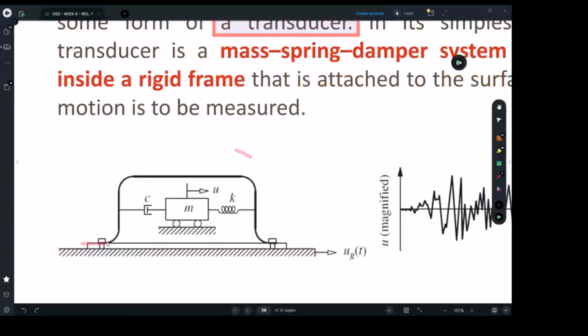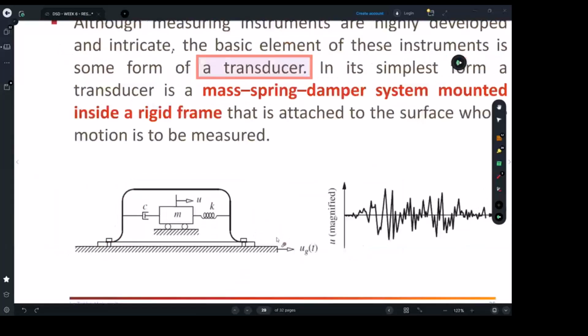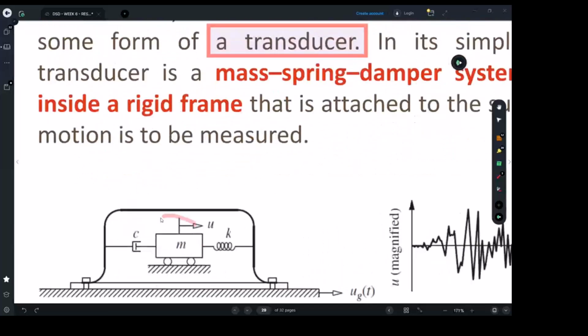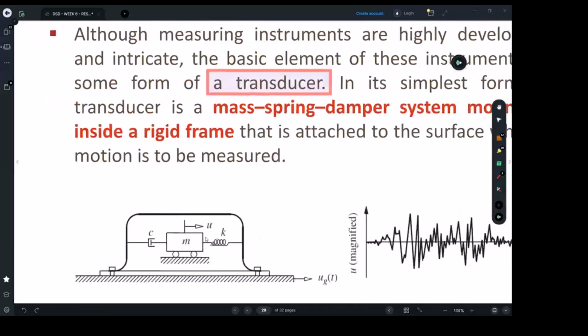So inside those equipments or measuring tools, whether the accelerometer I was talking about or the vibration measurement tool for earthquakes, it basically consists of a constant mass inside it. There is some damping to control the damping level, and there are some stiffeners, which is the spring.